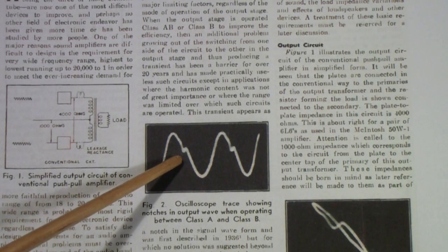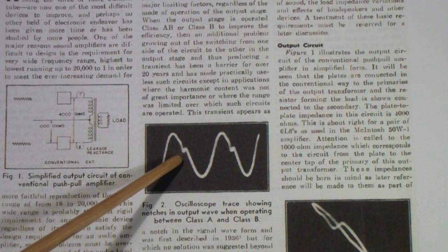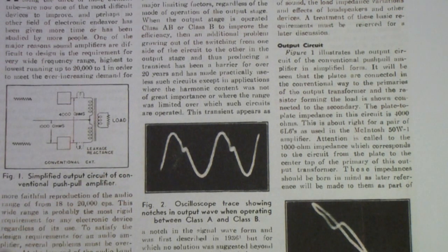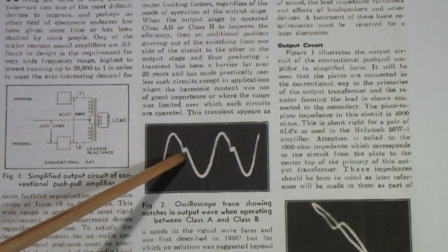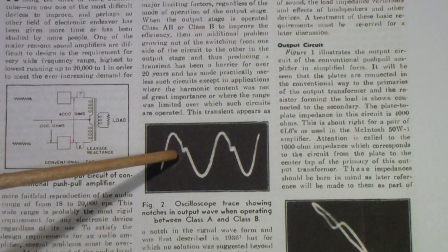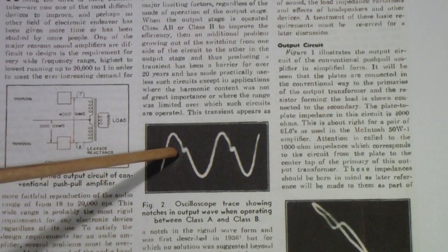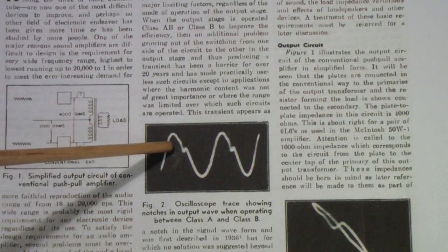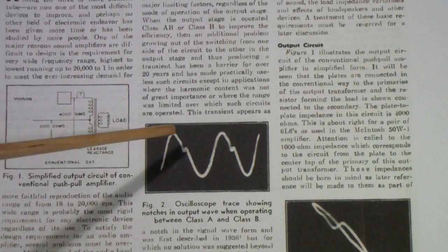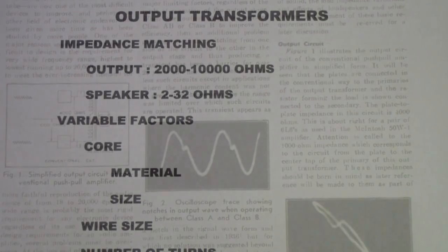So I'd like to talk about output transformers, but especially I'd like to show you about leakage inductance, how you can measure it, and how you can model it in a circuit so that you can predict ahead of time how much this particular transformer is going to add in inductive kick. Now, I emphasize that even transistor AB amplifiers have some crossover distortion, but tube AB amplifiers have an additional distortion produced by the inductive kick that is modeled using leakage inductance.